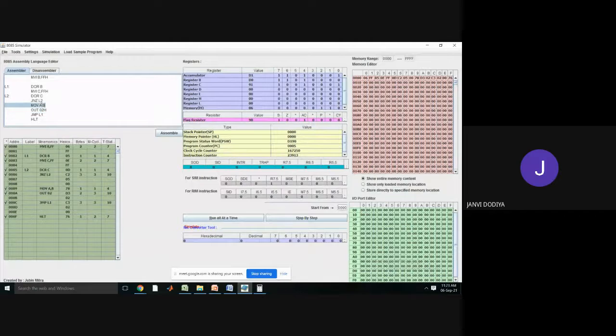Yes, ma'am, getting. Okay, so here you can directly take A. You can take MVI A. You will send it to the output port, OUT 0 to H. Then you are decrementing your A. MVI C, FF, ये आपका लूप किसके लिए है? You are taking that for the delay, right?